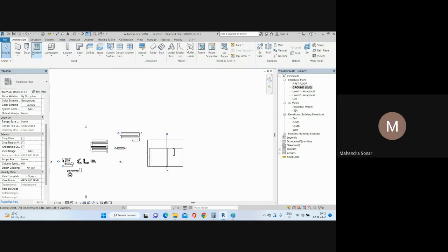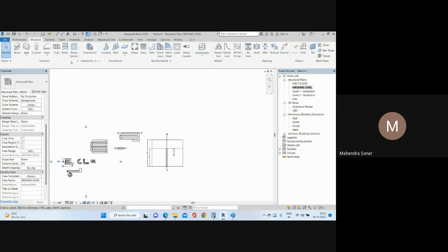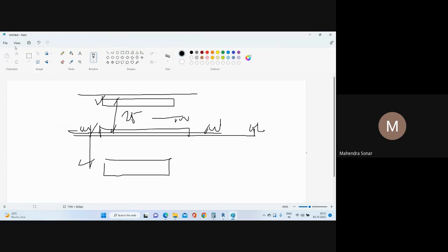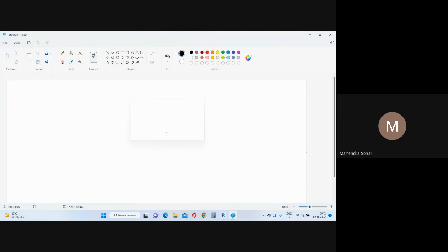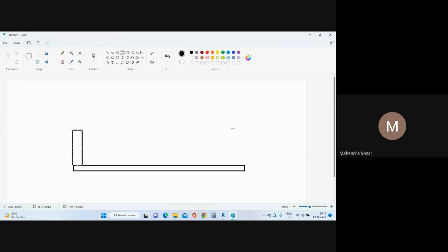Yes. So next in the architectural tab, roof we saw, then stair railing, then structural. If you go here, okay. So what we'll do? Today we'll start steel structure. Just consider we are taking one example. Our structure looks like this: just consider this is a raft slab. Then you can add some column here, a concrete column. And above that you need to provide some steel column, I section from that.